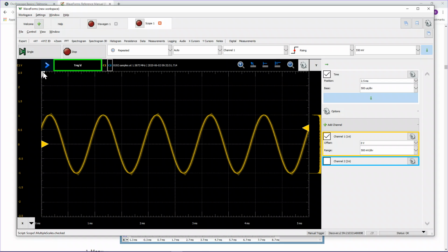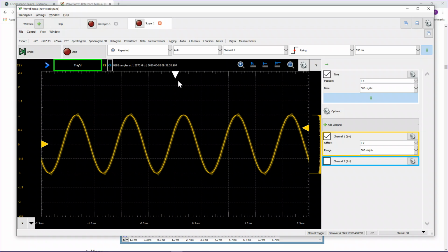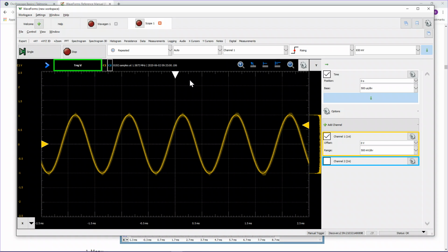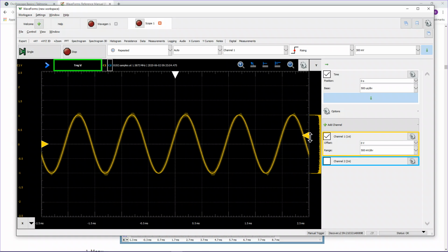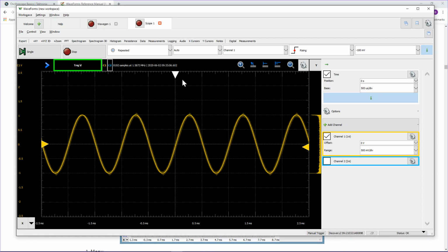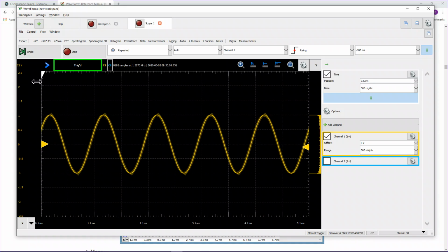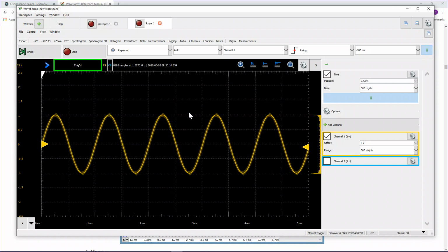By the way, you can change the triggering point to show up anywhere on the screen, and you'll notice now that when I adjust the voltage, the triggering point voltage is right here, and it's changing there as well. I sort of like it over here. Depends what you're troubleshooting on, what you get used to. You can put it anywhere that you want to.